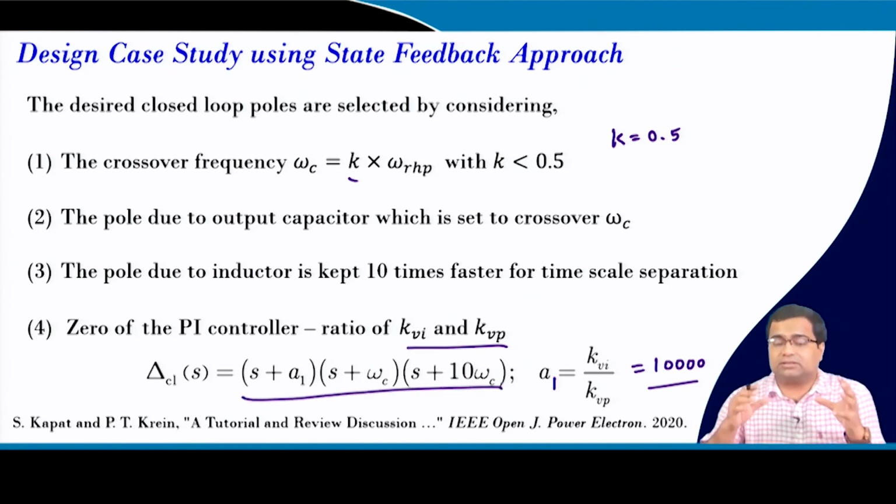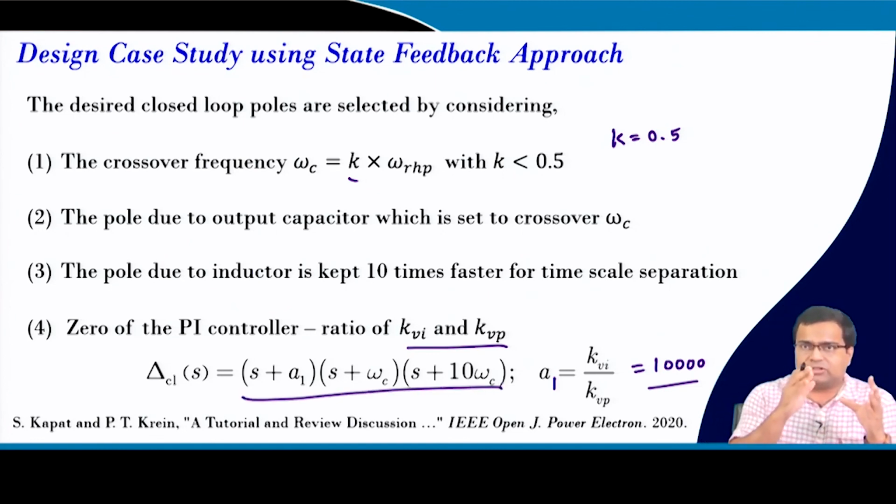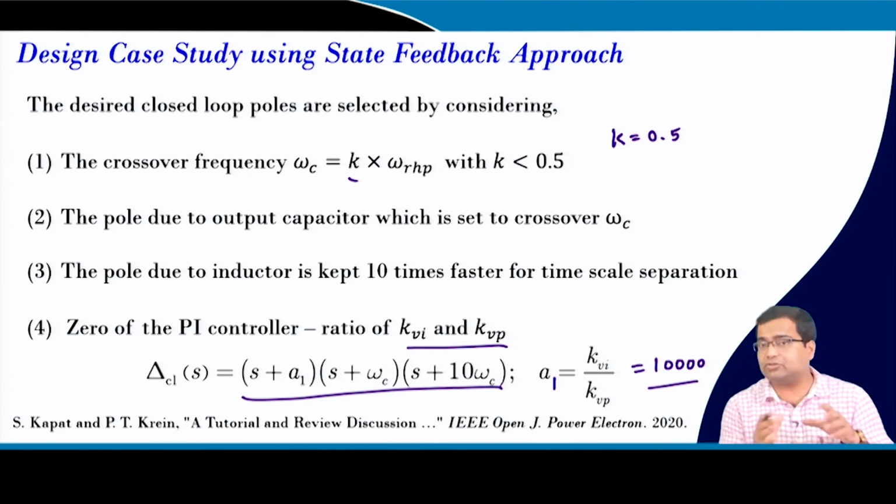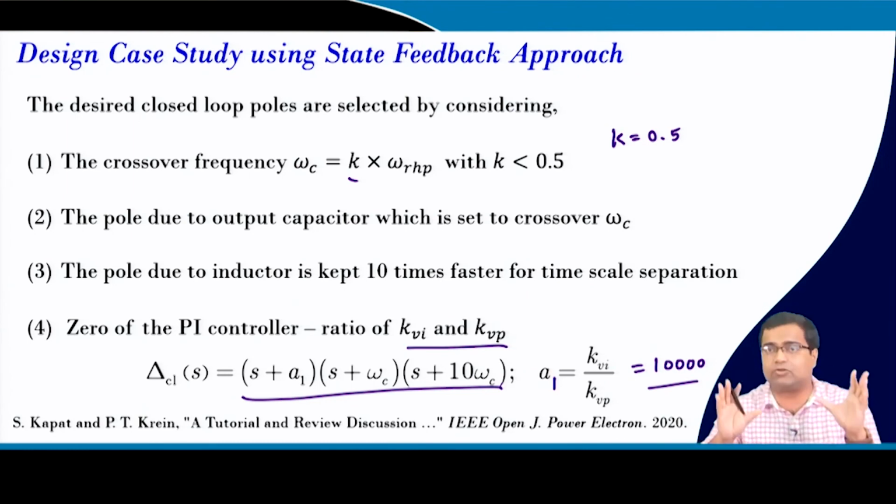That means in the earlier case there was a pole zero cancellation, but now it is not there. So, the whole system is perfectly controllable. Now, we can use optimal criteria, not only for performance improvement, we can set some optimal criteria like LQR criteria for certain cost function optimization. That kind of criteria we can use.